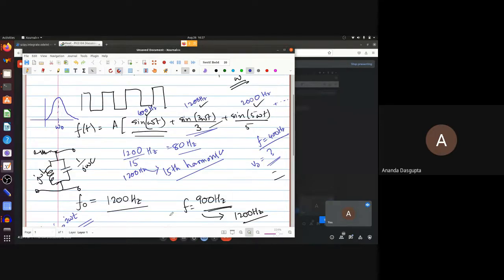And that is why what you have to do is think of the square wave as made up of many, many sinusoids. This is just a sum of a lot of sinusoids which are going in, and because your circuit is linear, you can find out the output for each of the sinusoids separately and add up the result.